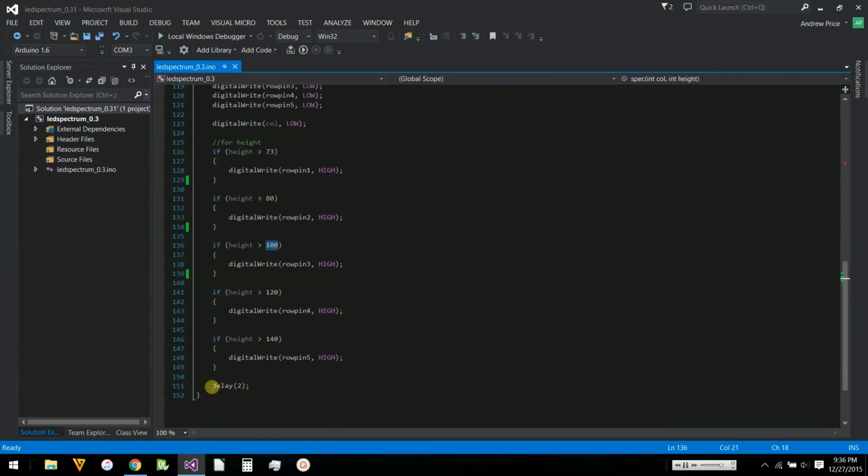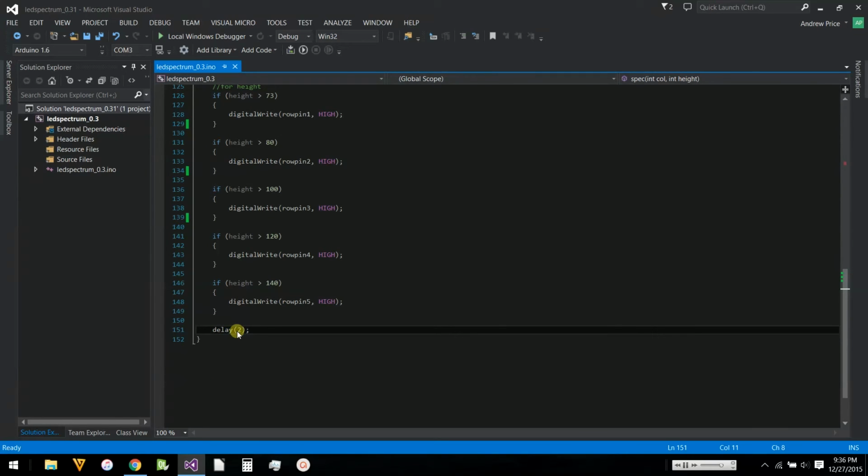So it delays at the very end after lighting up all the rows and the column, so that it stays lit. Try blinking an LED and delaying it, and around 6 or 4 you can actually see it blinking. Any lower than that, it looks like it's always on.